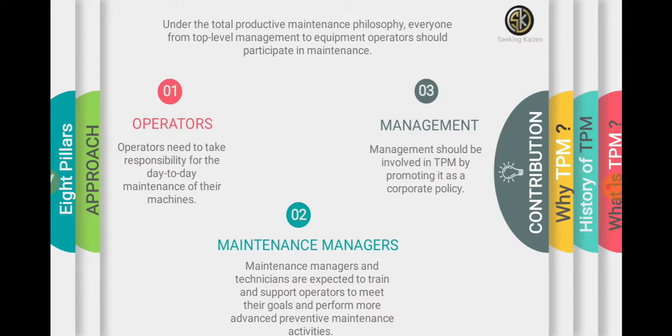He needs to take off all the covers, remove the dirty oil from the tank, and simply find the dirt. The word cleaning here is something like inspection, something like checking. So the operator needs to check for faults. He needs to find the dirt on the benches, beneath the machine, in corners, dirt and dust anywhere, in loose parts and leaking parts which are not noticed yet. Therefore, thorough cleaning should be there. The operator needs to get rid of dirt which has been accumulating over the years.